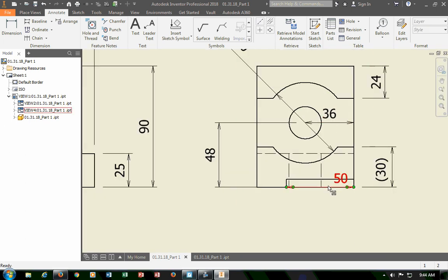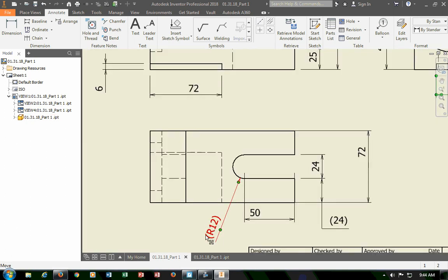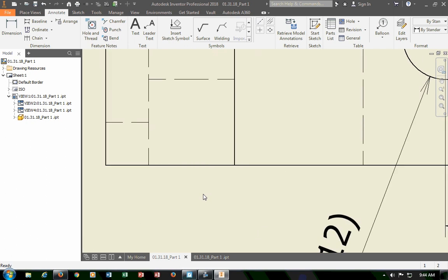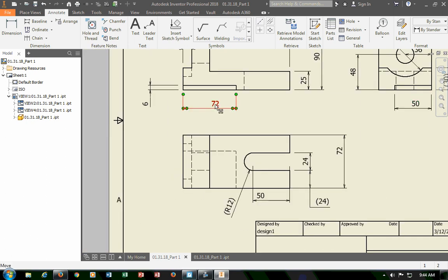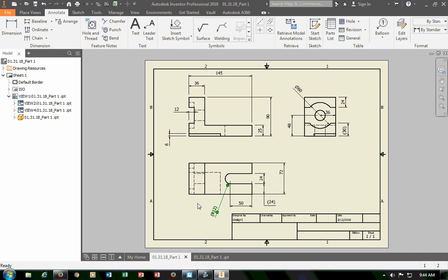So here we go. We drop some dimensions. Even in this view, this is a very difficult object to notice. I might say we're going to have to dimension that here. Those are the only, that box in the bottom. I don't like dimensioning to a hidden object because I can't see it. Drives me nuts. The other things that are missing, we'll wait on that for a little bit. What else is missing, people?